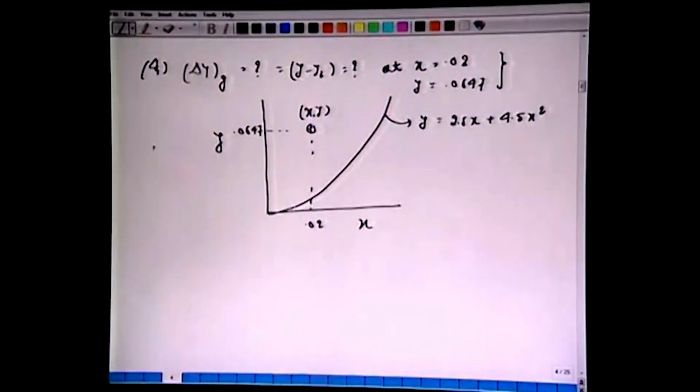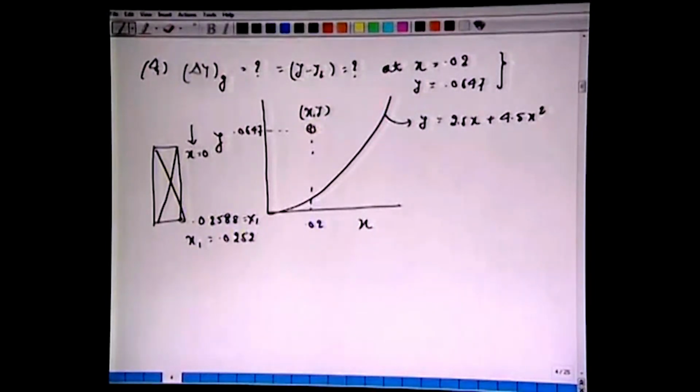In the absorption column, x varies in the liquid phase from x equal to 0 to the exit phase concentration we calculated, which was 0.02588. All right, this was 0.02588, that was capital X1, but we calculated the small x1 as 0.02523.